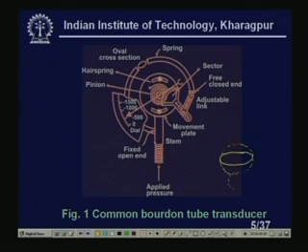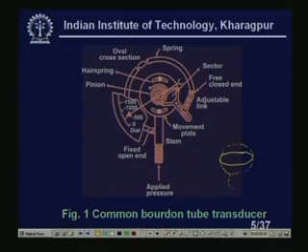It is a very widely used transducer, I should say, for industries. From a cycle store to any process industry, you will find it, with a very wide range. It can measure the pressure of corrosive liquids also, and gas. Starting from liquid, gas, air, everything we can measure with this. Over the years people have been using it, even though this is basically a monitoring instrument, not a transmitting instrument. Since the tube is a C, we call it the C-type Bourdon tube.